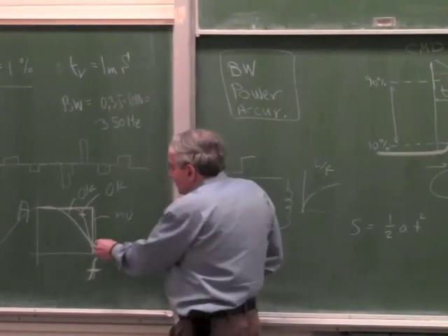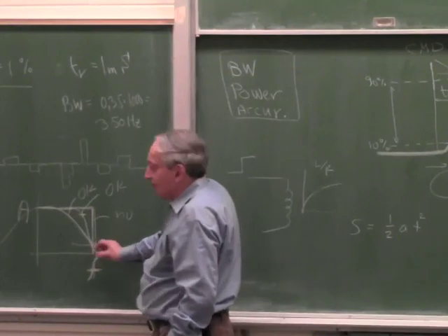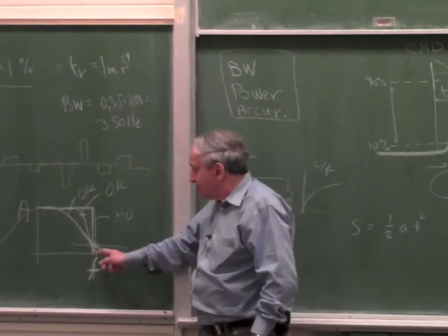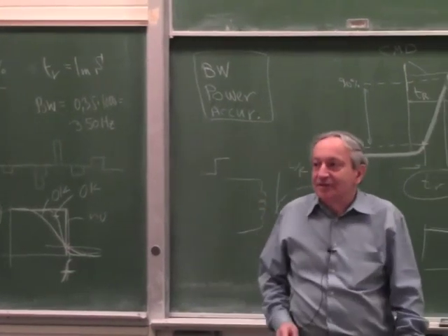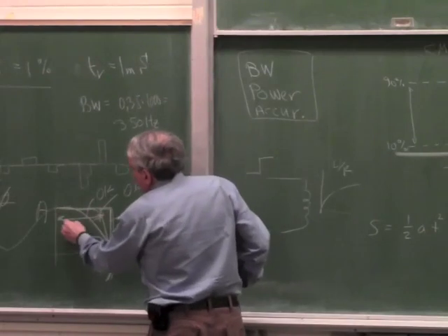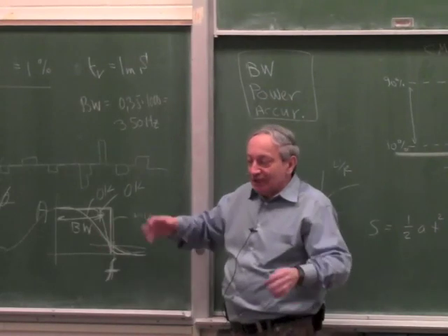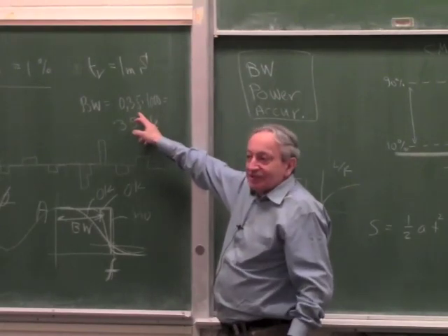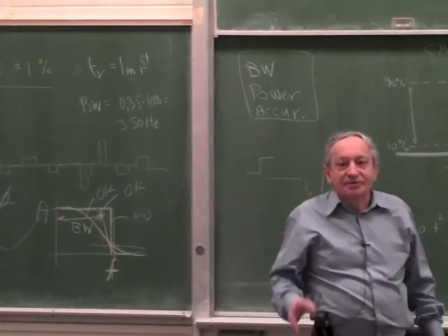So the most important point is here. Let's say I want the filter to cut off at a certain frequency to a certain amount. So does somebody remember how do I know at what frequency the filter should cut and to what amount? In order to specify the filter. Because the bandwidth of the filter is measured here. This is the bandwidth of the filter. The bandwidth of the filter is usually measured to the 3 dB point. Okay, so I can easily calculate the bandwidth of the filter. It has to come out a bit more than this. But how do I calculate the cutoff of the filter at the bottom? So can somebody remind us?